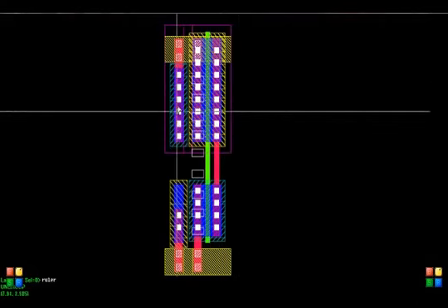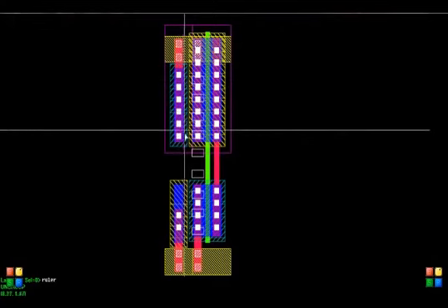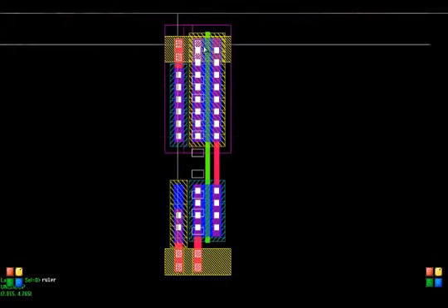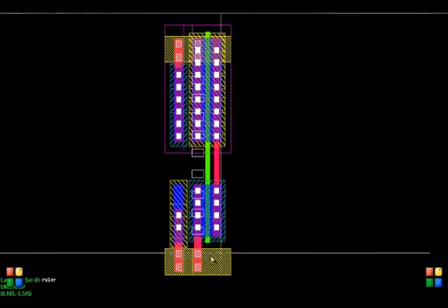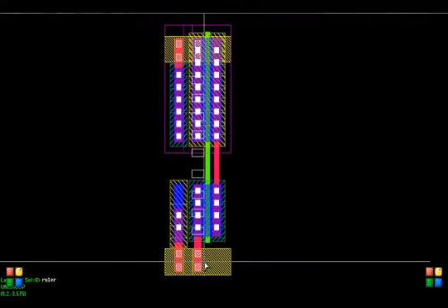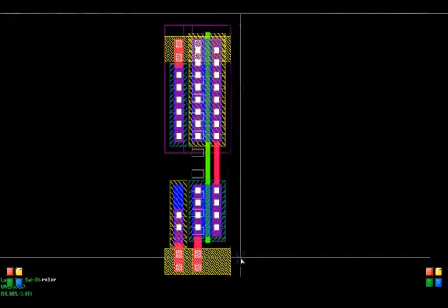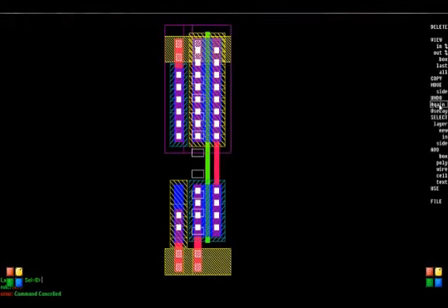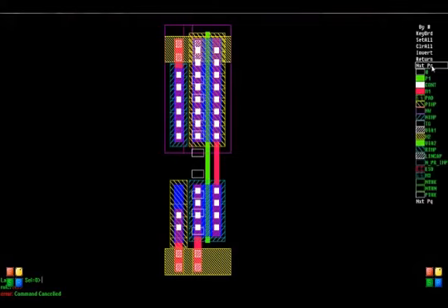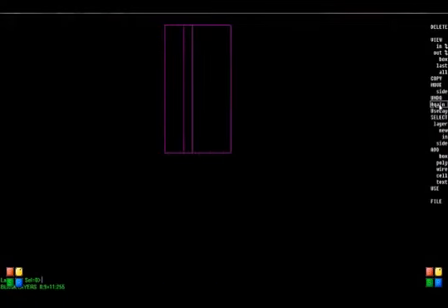Now this region here provides a connection to this N-well and connects it up to my power supply. This is my high voltage power supply up here, and this is my low voltage power supply. And we'll explain this in more detail. Let's turn off some of the layers and look at each masking layer for this inverter. So let's blank layers and well invert return. So now I'm just showing my N-well layer.